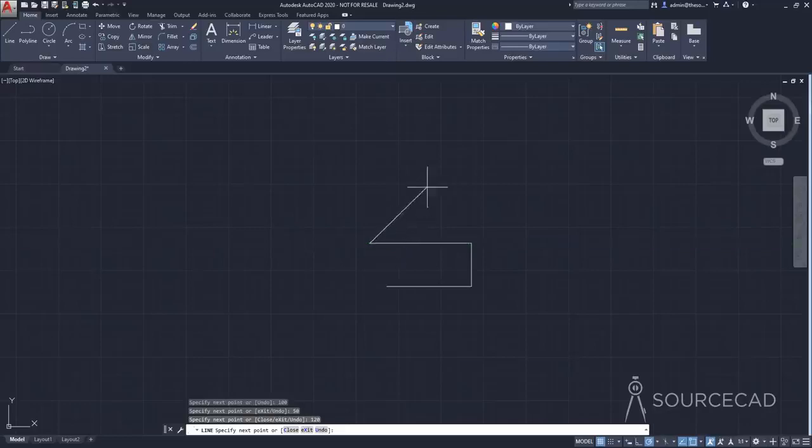And you can even align it in any direction if you want. So I'm going to align it here. I'll type 60, enter, and so on. So you can keep on making your lines by entering the proper distances, and it will just make your line that way. Also in this case, if you want to add angle values, then that also you can do pretty easily. So in this case, let's just make another line of length 100. So I'm going to go to 100 and enter. Now this length is again 100.